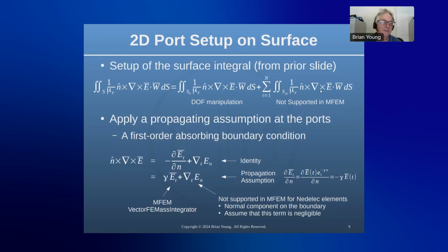High frequency depends on the dimensions of the problem, and in the problems I've run, the frequency range is appropriate for that problem, and so far I haven't seen issues. Calculating S parameters, you're bringing in single mode operation anyway, and in any engineering application, you're just not going to push it to a high frequency that's not appropriate for the structure you're trying to test. So that may be why I haven't seen it. I'm using frequencies for which the problem is designed.